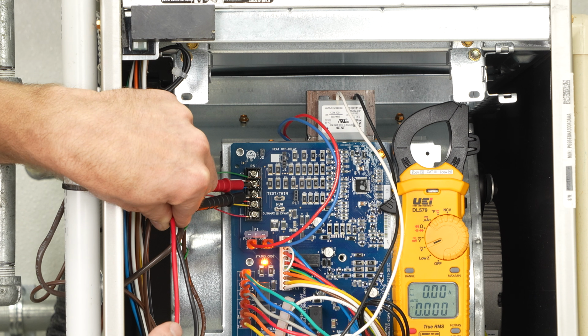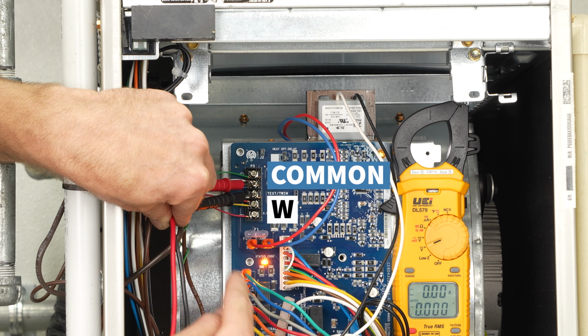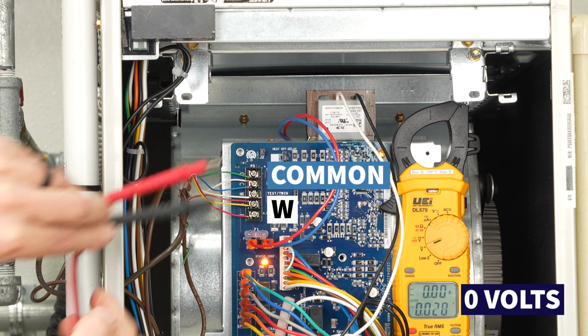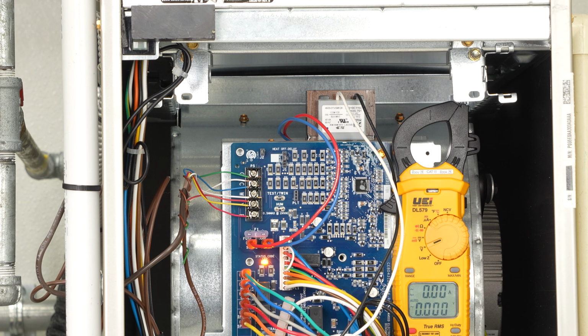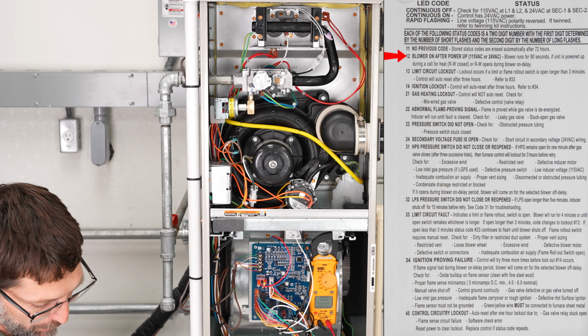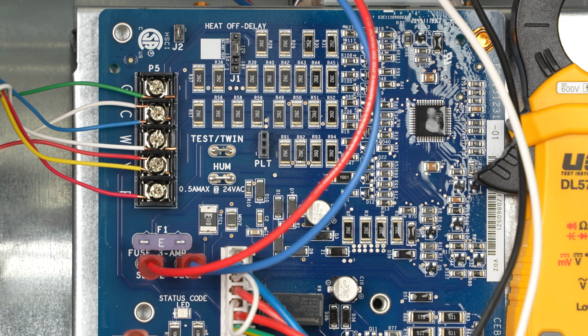In order to do a component test, you cannot have a call for heat to turn on. So right now we're on the W and the C terminals, and we measure 0 volts. So that means the thermostat is not calling for heat to turn on. And also, when I do start the component test, you're going to see an error code status light of the last error that we may have had, which is likely going to be a number 12, which is a blower on after power up. So here you see your status code light. Then after that, the inducer motor is going to turn on.